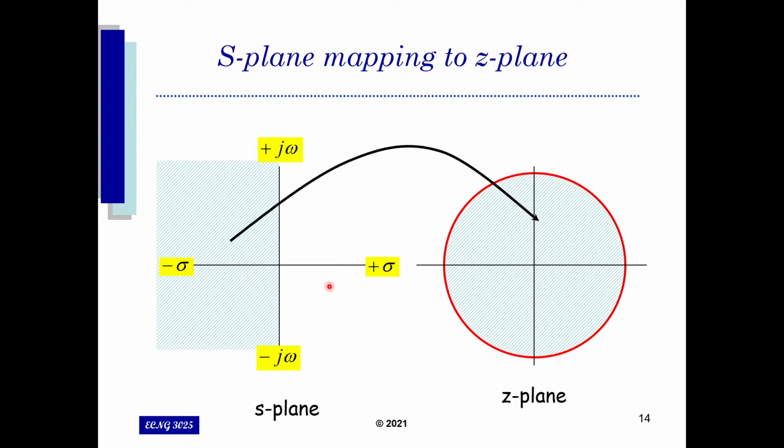We know that for a system that needs to be stable in the Laplace domain, all the poles need to lie on the left hand side of the Laplace domain. Transforming this into the Z domain, that means for a stable discretized time system, all the poles must lie within the unit circle in the Z domain instead.